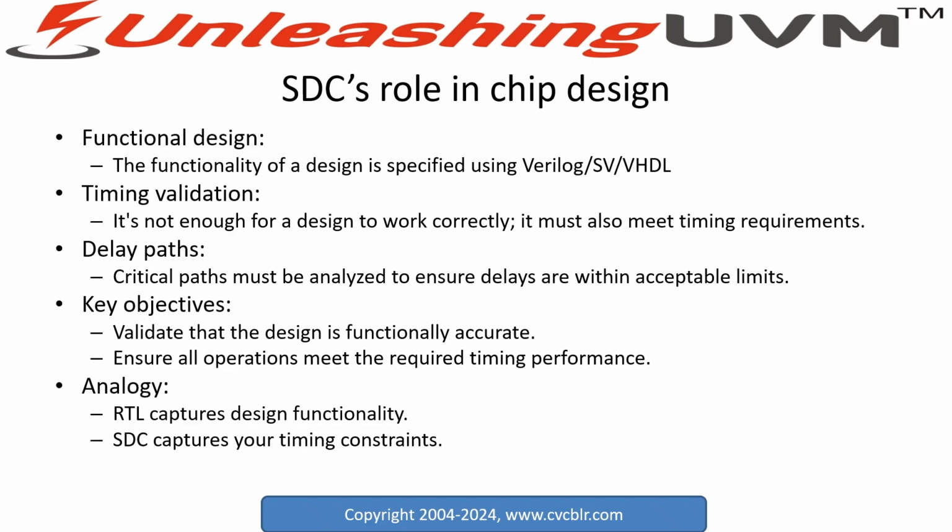There are also delay paths. At RTL level, we really don't do a lot of delay calculations because we tend to say register to register, and hence it's called RTL. But then there are critical paths that must be analyzed to ensure delays are within acceptable limits. Again, we are not going to do the traditional gate level with SDF in this particular context.